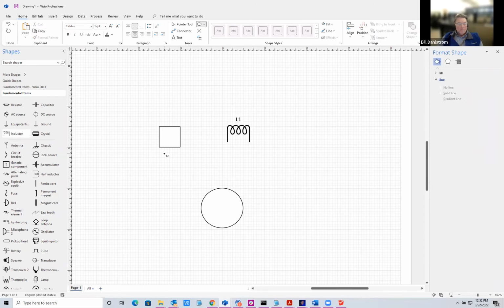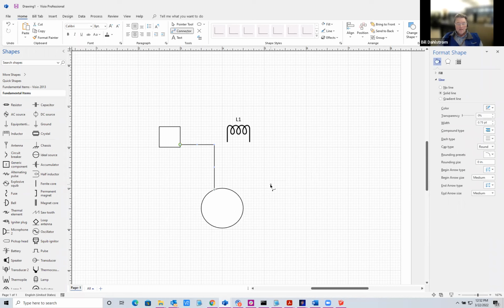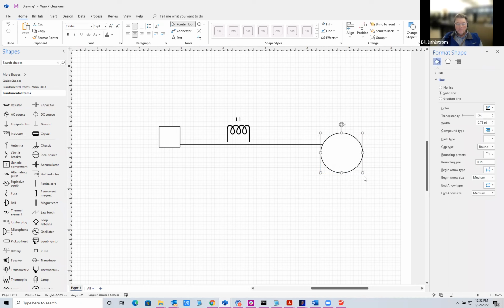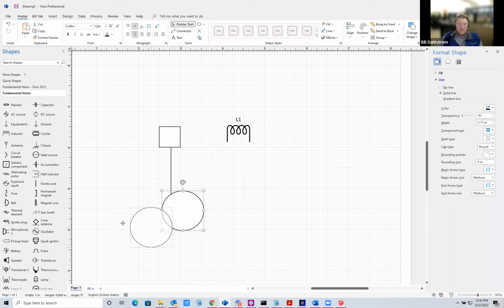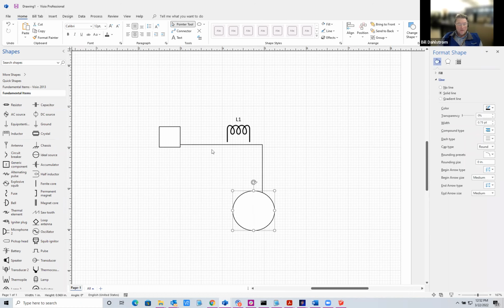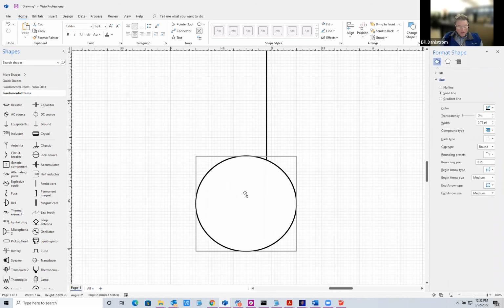Because of glue and snap, if I take just 2 drawings and I want to draw from this one to this one, it makes a line in a pretty arbitrary place. And if I grab this and move it, the line moves and connects to a different spot. So what you do is you go up here to this little X, and on this highlighted shape, I push down the control key and I can add a connection point. I added that connection point and that line snapped over to it.